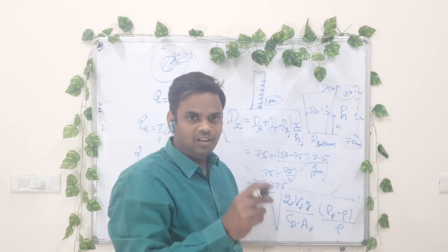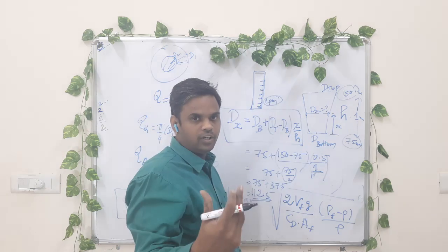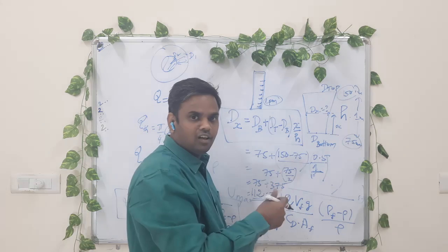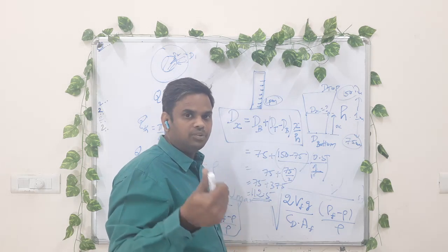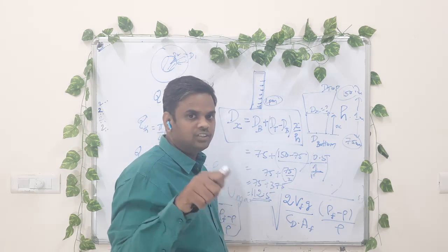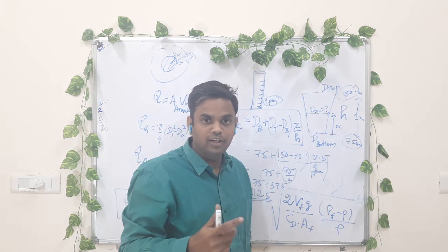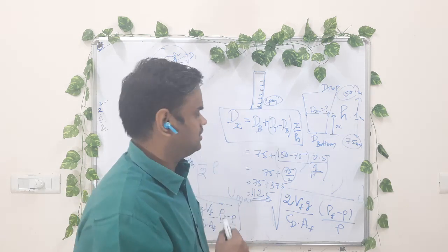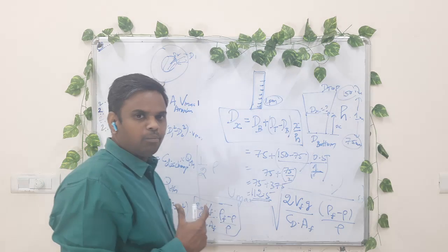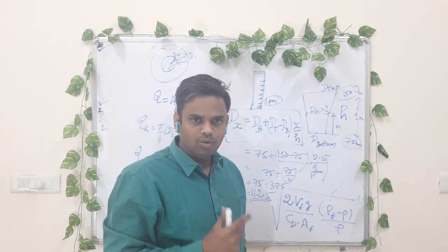I hope you might have been adjusting a knob to fix the float position to fix the flow rate. So by changing the knob valve, by opening the valve into different positions or bypass valve positions, we will be fixing the volumetric flow rate at which the fluid is flowing. So that way it is used for both liquids as well as gases. That is one of the important variable area flow measuring devices, which is called a rotameter.